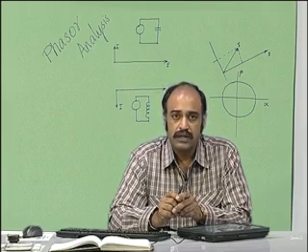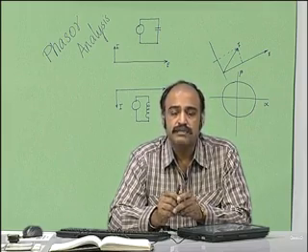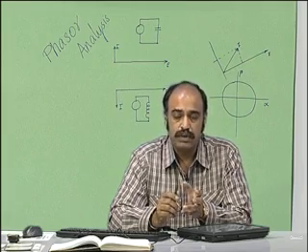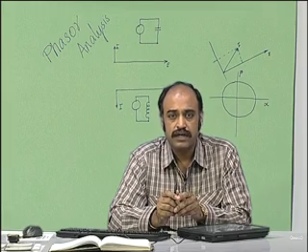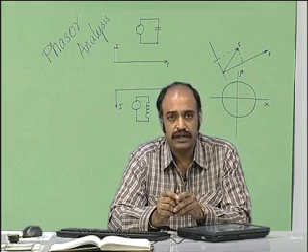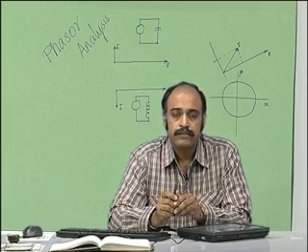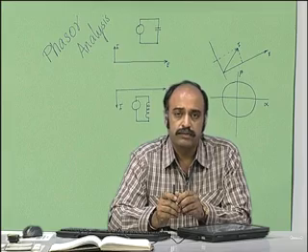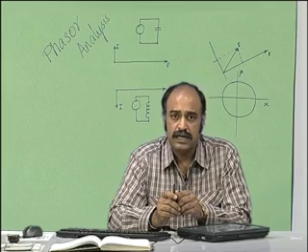So, you could have the voltages, currents in various branches. How are these various currents and voltages displaced with respect to each other in a phase shift manner, that is the phase shift between the two waveforms. And then what is the active component of the power, what is the reactive component of the power, all this information can be obtained from the phasor analysis.